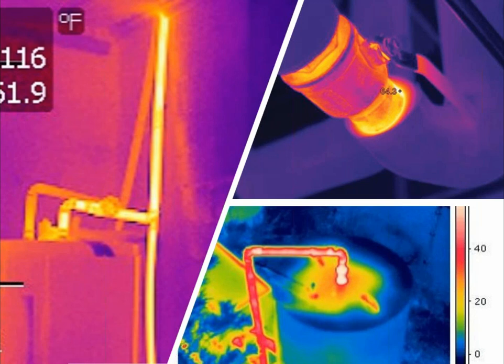So primary loops are one thing, but let's talk about stagnant heat losses and standing heat losses on stationary geysers. When I say stationary, I mean geysers that are standing overnight. Nobody's using any hot water. There's no water flow. So in this image on the left here, you'll see that somebody is obviously using water. The entire pipe is warm. Likewise on the one lower right.